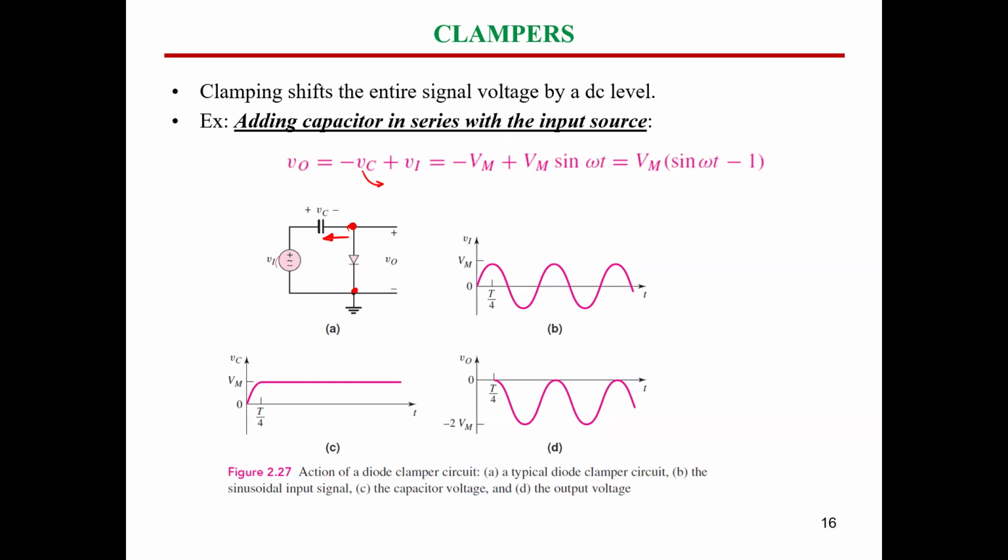So now let's substitute in this relation. vC plus vin. So vin is nothing but a sinusoidal supply, so it's Vmax sin omega t. And when you charge this capacitor, when the circuit starts working, firstly the supply volts start from 0 like that, and it will increase.